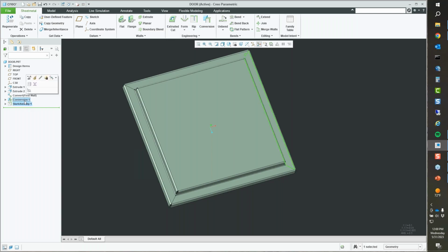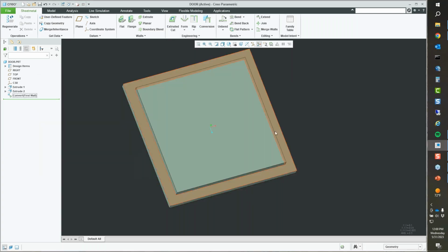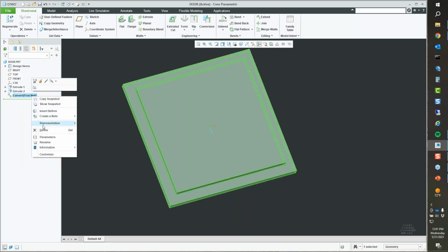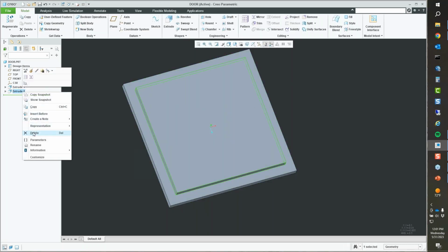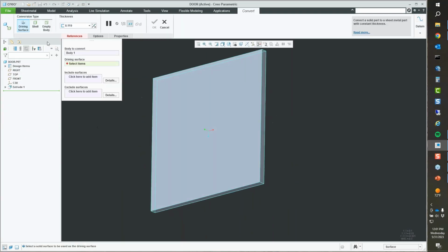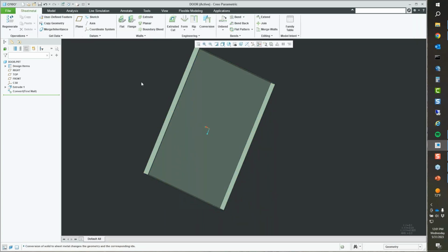Without the conversion tool, let's say we did this, you can, I'm actually gonna, let me go back here a little bit more. Delete, delete, delete. Let's convert just to one panel here. Operations, convert to sheet metal, shell. I'm just simplifying it to make it a little bit easier this time.